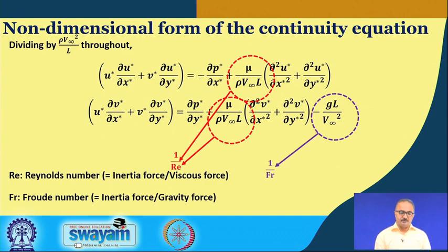It will stay in the turbulent region. Similarly, we have another number we call the Froude number, and this Froude number is the ratio of the inertial force to the gravity force. Now, gravity force comes into play, for example, when you have waves on a river or in some kind of channel. These waves are formed due to the gravity effect. You can see that waves come and then they fall. Okay? So this is due to buoyancy and gravity. So this buoyancy or gravity effect also comes into the picture in dictating the motion of the fluid, other than the inertial force.